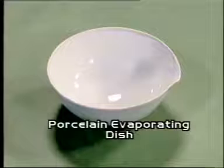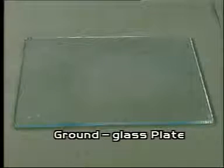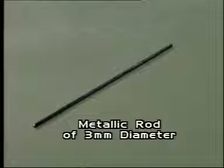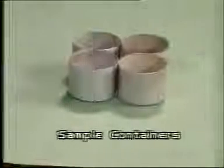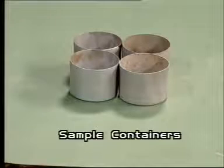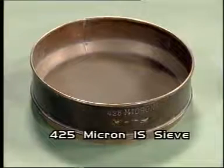Plastic limit of a soil is the water content at which a soil just begins to crumble when rolled into a thread approximately 3 mm in diameter. The apparatus required for conducting this practical include porcelain evaporating dish, ground glass plate, metallic rod of 3 mm diameter, spatula, sample containers, thermostatically controlled oven, and 425 micron IS sieve.